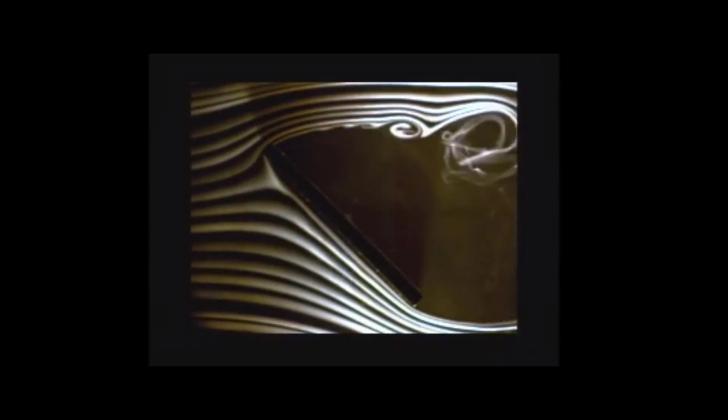A path line is the actual Lagrangian path traversed by a given fluid particle. It can be observed in a time exposure of a single marked particle moving through the flow. In steady flows, streamlines, path lines, and streak lines are identical. A timeline is rather different. It is a line of fluid particles across the flow at a given instant, and it reveals the velocity profile.